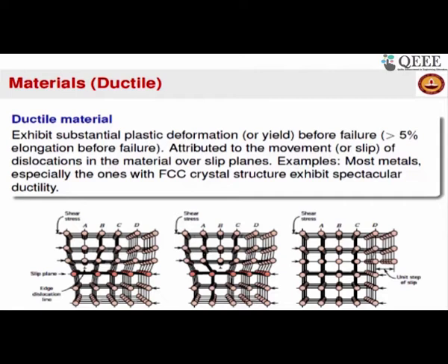Okay, it will just move like a caterpillar in a wave-like motion and result in some sort of permanent deformation with one unit cell protruding out. If you can see slide number 16, it is going to be a little more clear. So this slip on application of the shear stress or loads is actually causing yielding or ductile behavior.